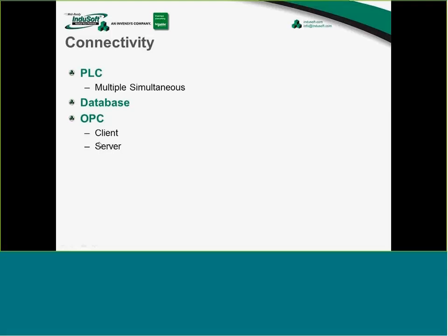Well, let's turn that around a little bit. InduSoft Web Studio can actually be an OPC server. So maybe you have connections to PLCs, databases, and OPC servers through the client, and now some other piece of software wants to come and collect that information out of the InduSoft running application. Well, we can be an OPC DA server and have anybody else's third-party client come along and collect tag information directly from us. So a lot of connectivity options there.